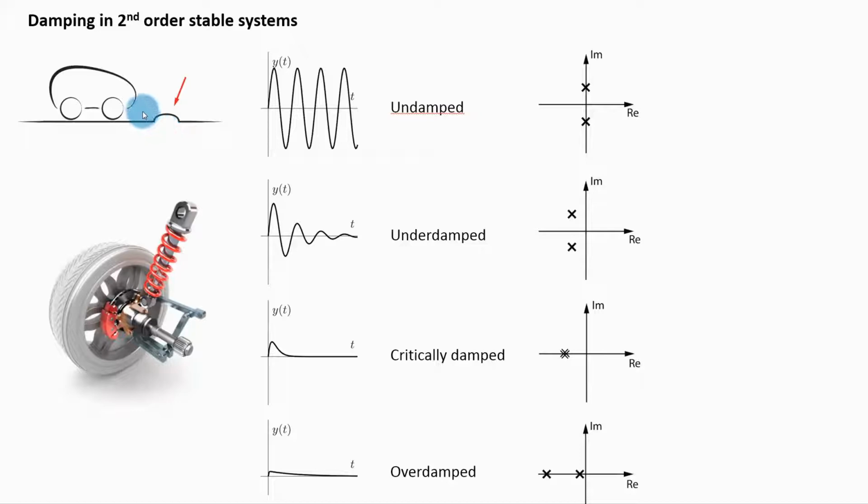Well, if the wheel axis was firmly fixed to the rest of the car, the entire car would jump. That is definitely not desirable, therefore we use wheel suspension, where the wheel can move up and down with respect to the rest of the car, and the wheel axis is not firmly fixed to the rest of the car, but it is held in position by a spring that can compress and extend. So when this wheel hits a bump, this spring compresses and only the wheel goes up, not the entire car.